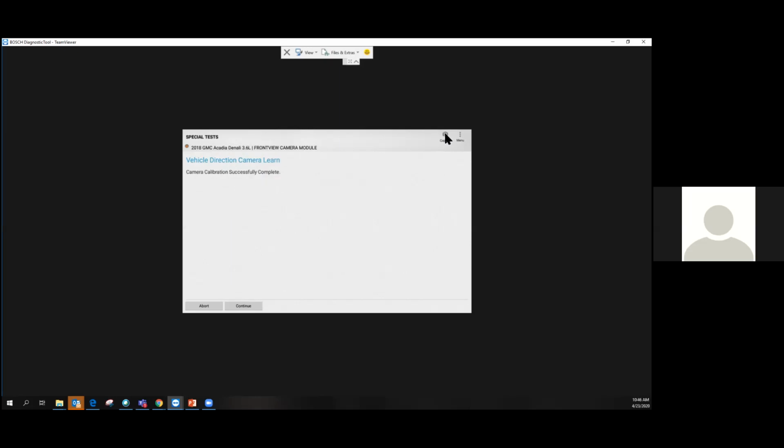There's a couple reasons to do this. We want to get paid for it. So if I need to prove that I've done this and document it, well, I can drop this photo into my estimate like any other photo. And then liability, right? We got to cover our butts nowadays. So if I need to prove 6 months, a year down the line, if the system wasn't working properly, or they claim it wasn't working properly, I'm going to have a couple things going for me. I'm going to have my date and time stamp post scan. That's going to show that when this vehicle left my shop, there was no fault codes. I'm also going to have documentation of any necessary calibrations that were part of the repair procedure. So I always recommend take the screenshot, document it from here.